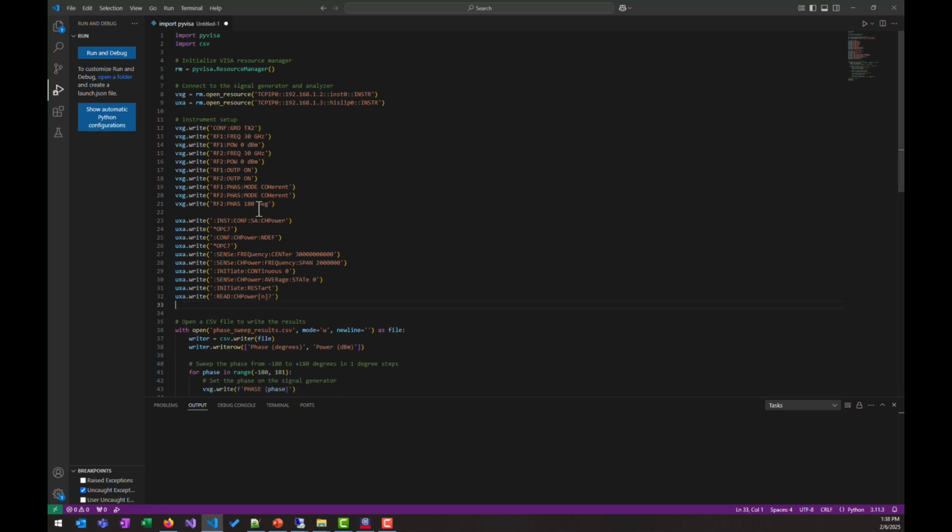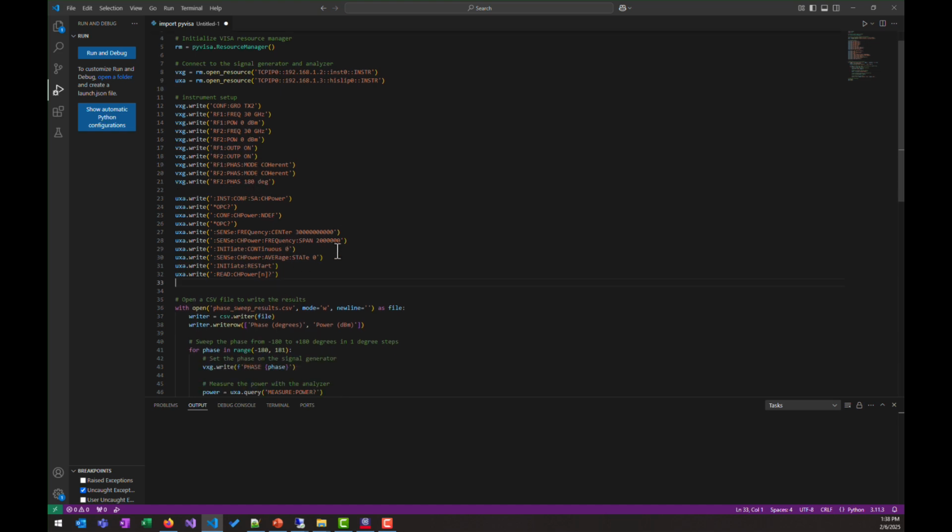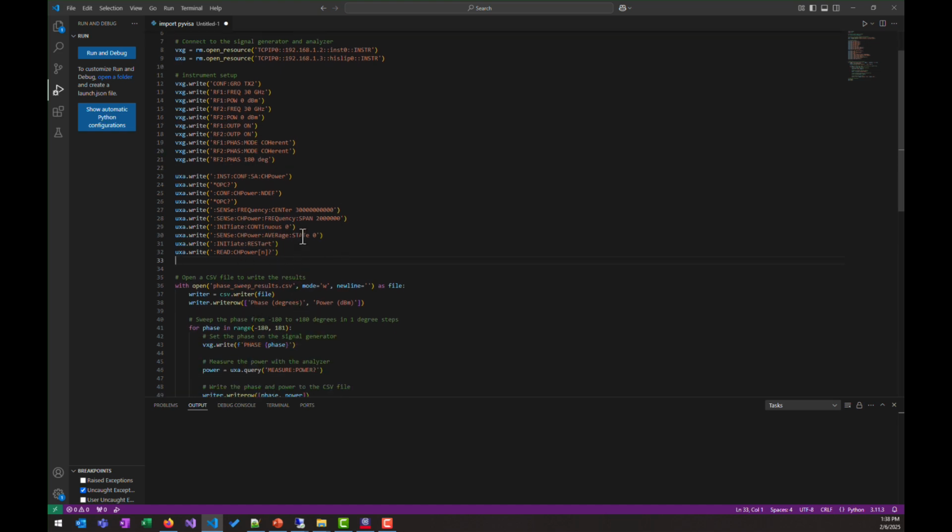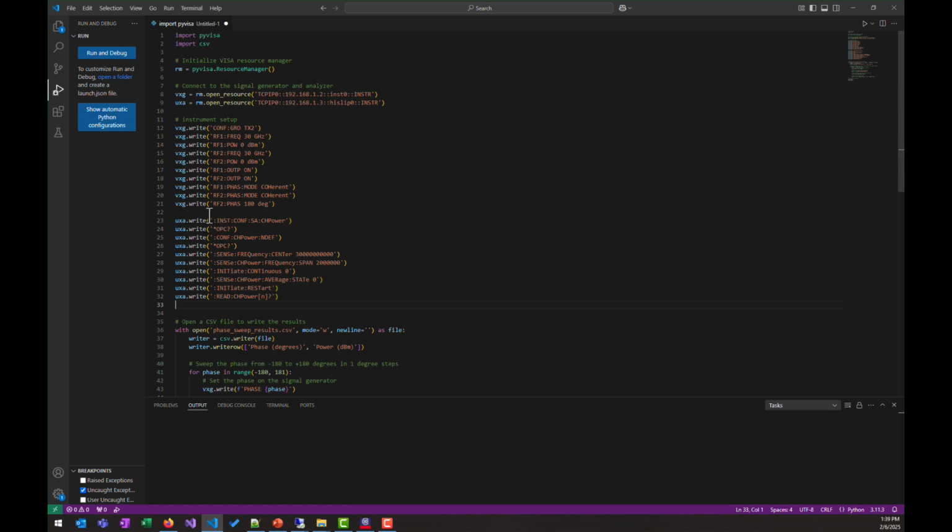And let's take a look at these commands, because some of these should be sitting inside of the measurement loop, while some of them should be sitting here in the setup portion of it. And one thing to note here is that these OPC question marks should be changed to queries. So anywhere you see a question mark, you should treat that as a query. And I know this command I manually looked up. I can remove this n argument here.